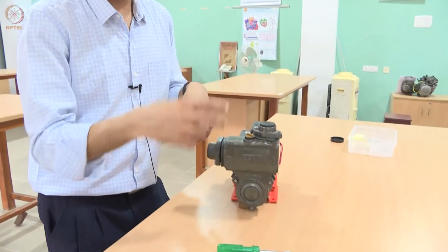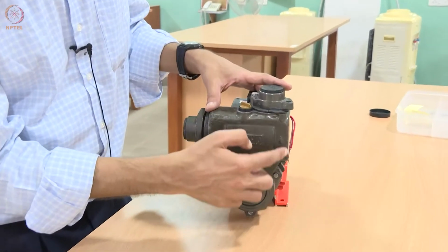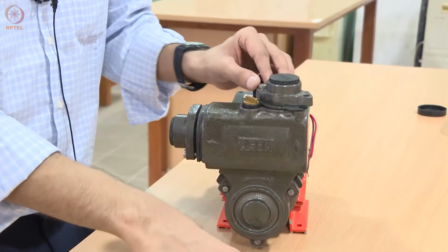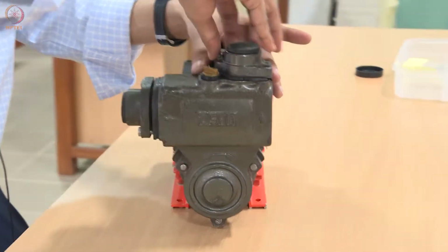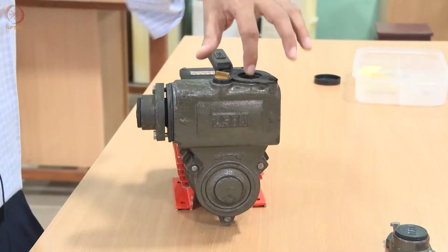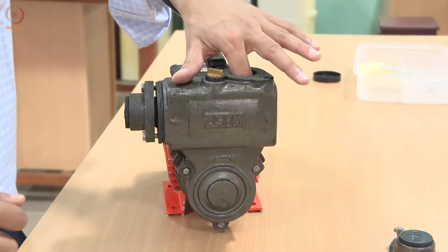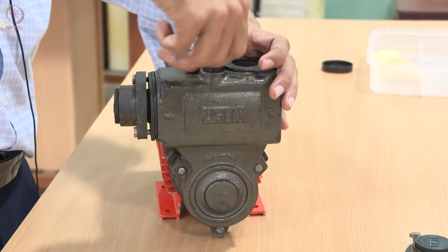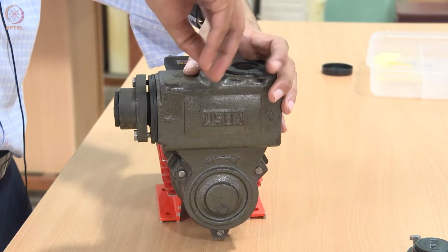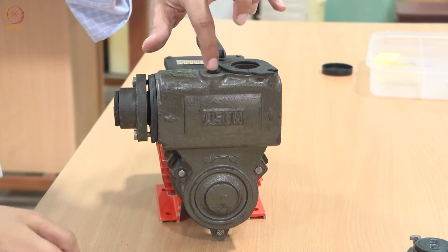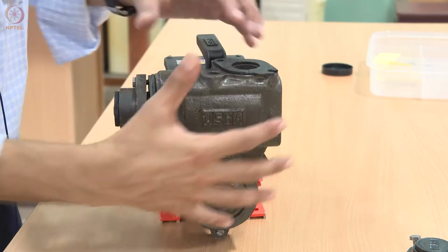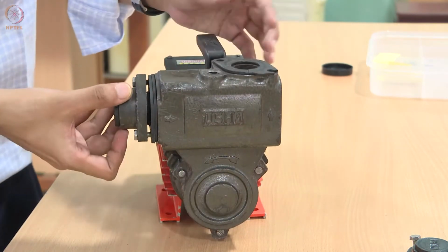But today we are going to look at a special type of pump. This is a pump wherein you don't have to fill the entire suction line with water. It is only enough that you fill this portion just by removing this. You just have to fill only this casing, maybe half a liter of water you pour in. So you have a separate provision for that. You open this, you put a funnel, and then you fill it with water, only this portion. So this is the suction line.